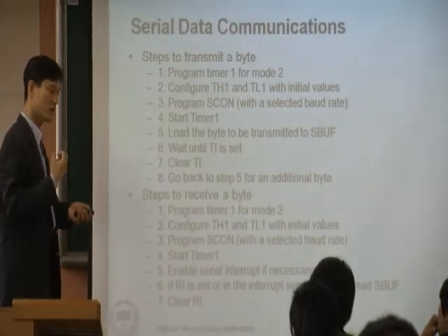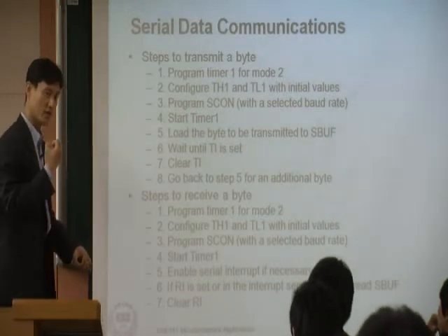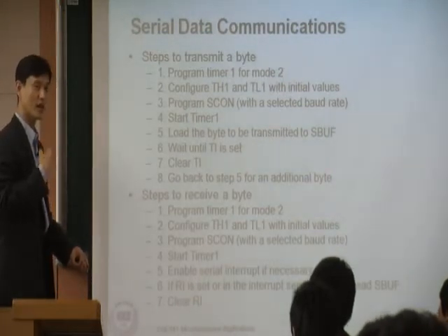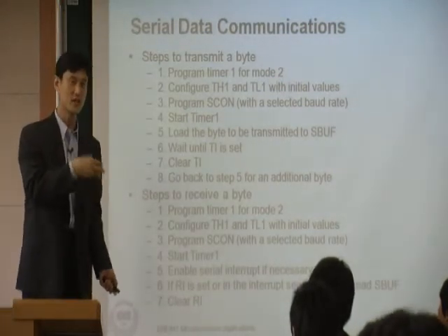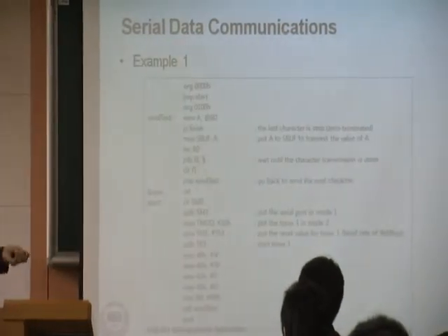So when you read it, of course you have to clear RI first, and then you read it. Then what do you need to do? Again, you have to watch RI until you read the next letter. That's what you need in serial communication.